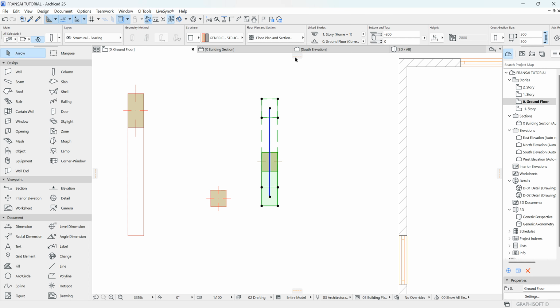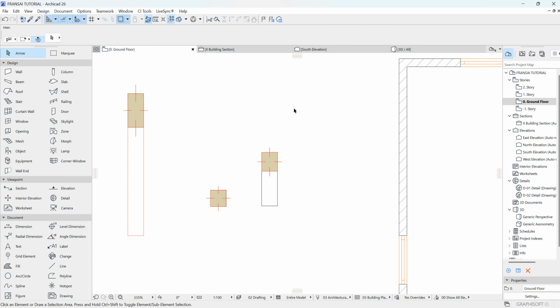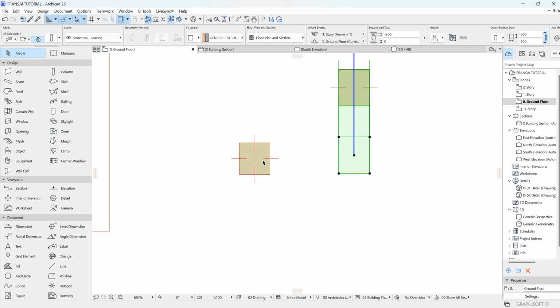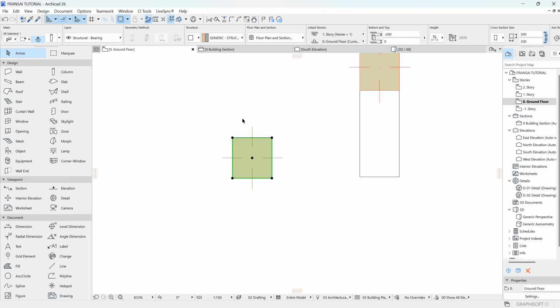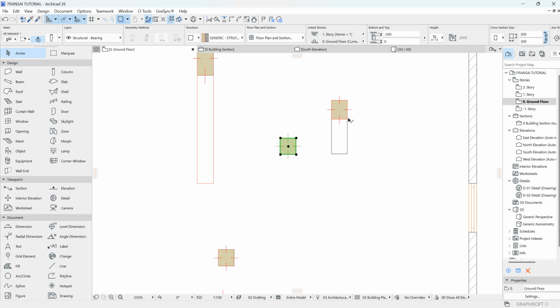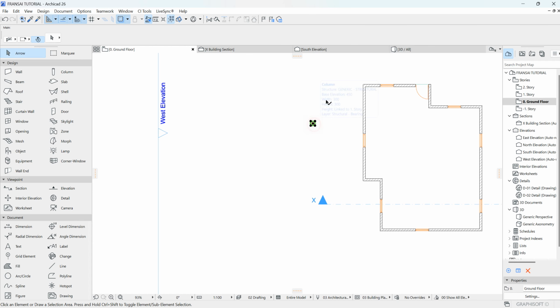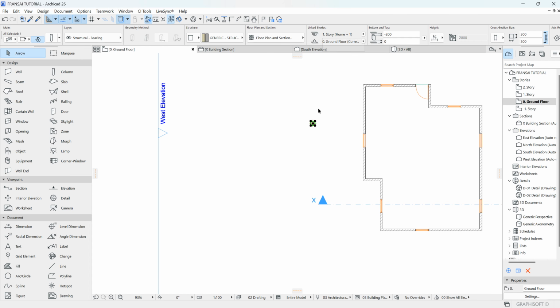The same thing works with the beam. That's why I've merged them together. Just that one is a horizontal member, the other one is a vertical member. That is the only difference. Okay, now this is another key thing again. This determines the height of the column. You can see it's locked at 2.8. It's because it's linked to the first floor, which is what it's supposed to be, and it's also linked to the ground floor. Let me delete these other ones. Okay, this is the only one now. It's linked to the first floor, it's linked to the ground floor.